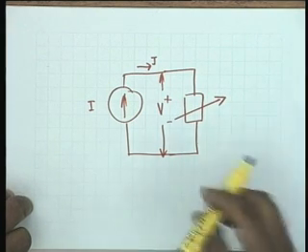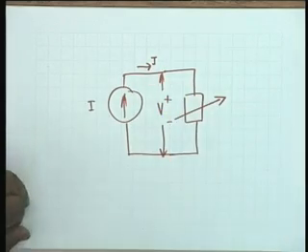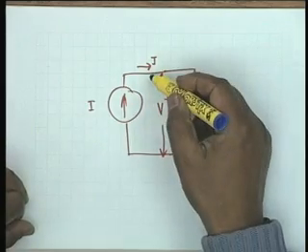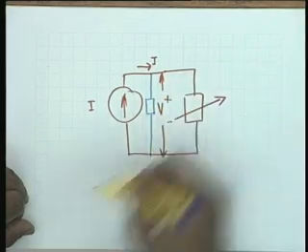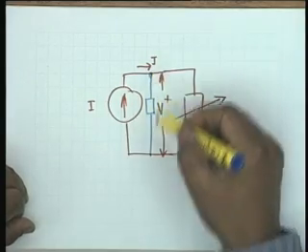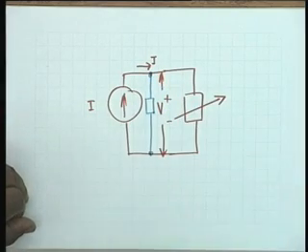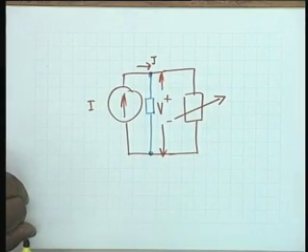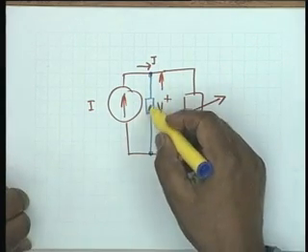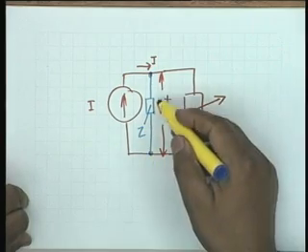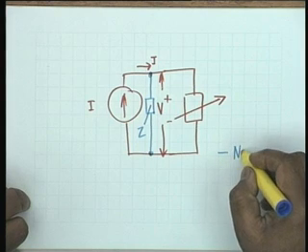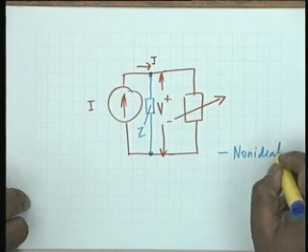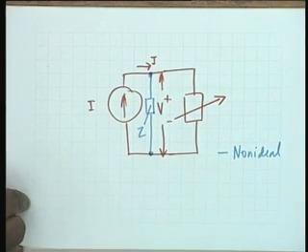On the other hand, if this voltage changes with the load, that can be accounted for by a shunt admittance, which in the case of a resistive current source will be a resistance, and it can in general be an impedance. The blue color takes care of non-idealness, the non-ideal current source. A non-ideal current source is an ideal current source in parallel with an impedance.